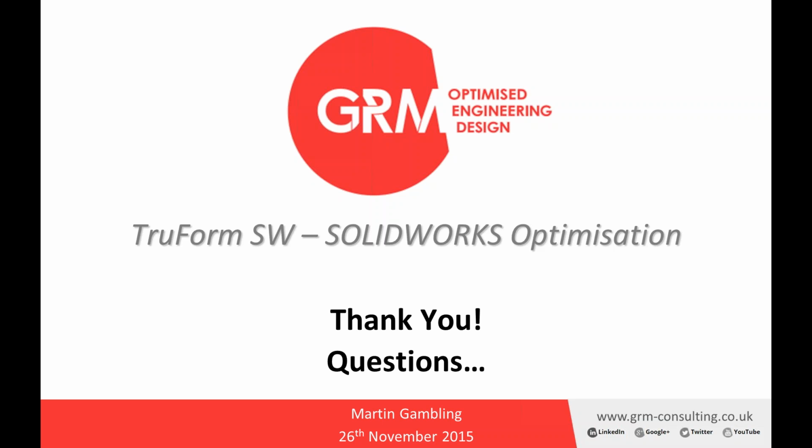Okay, good. And I have one more question here. Can you optimize in assemblies? Currently, I think technically it will let you try, but it's not something that works as it should at the moment. So I'd recommend optimizing with a part for your components.